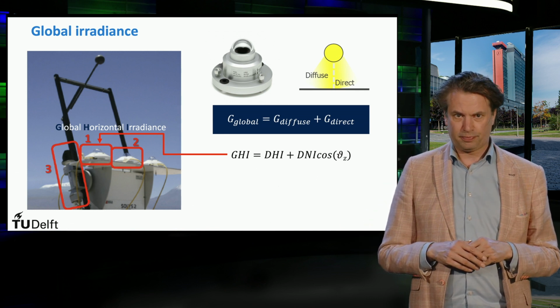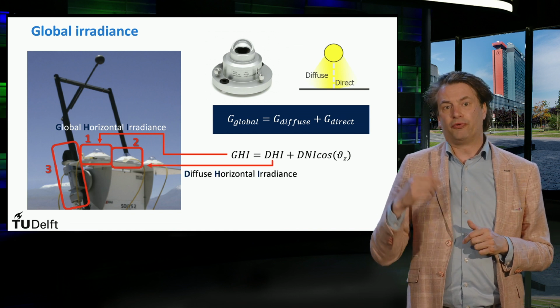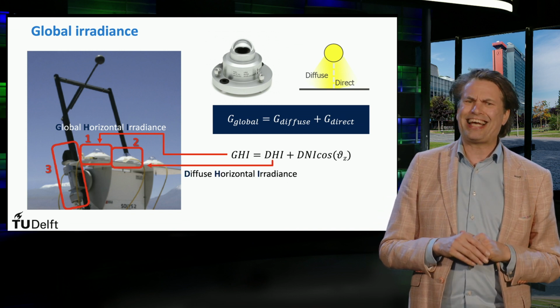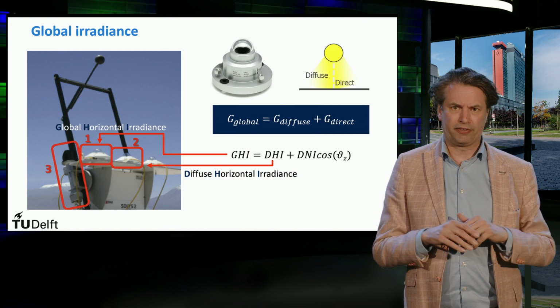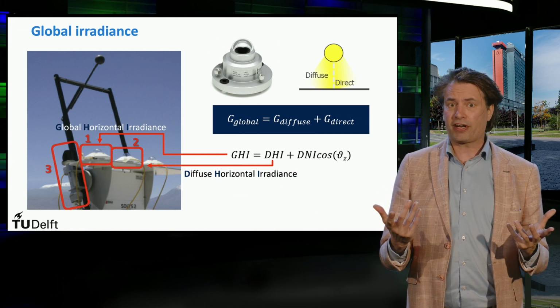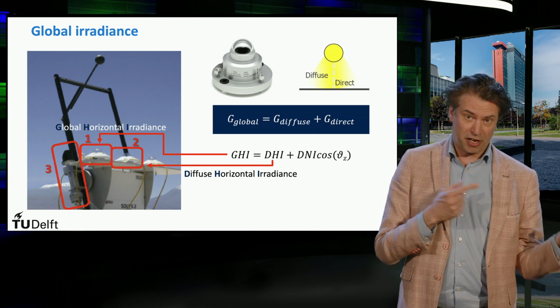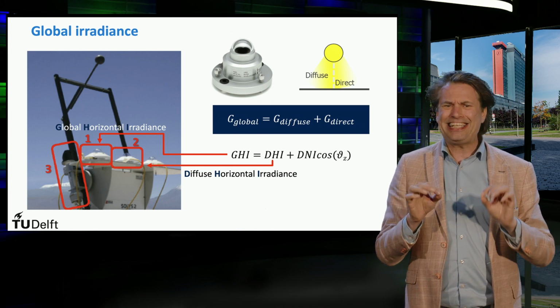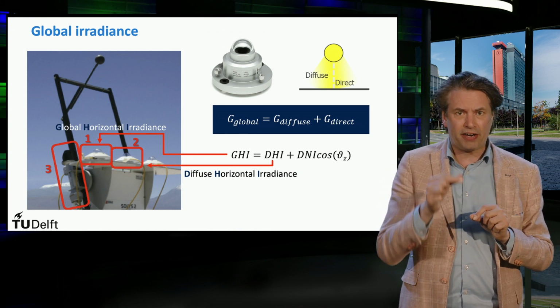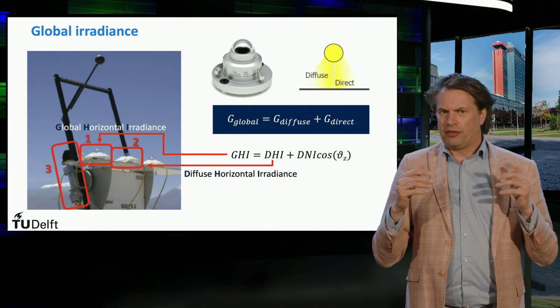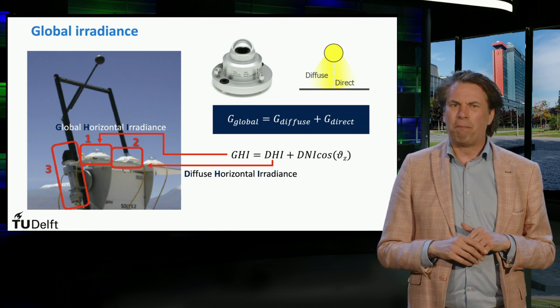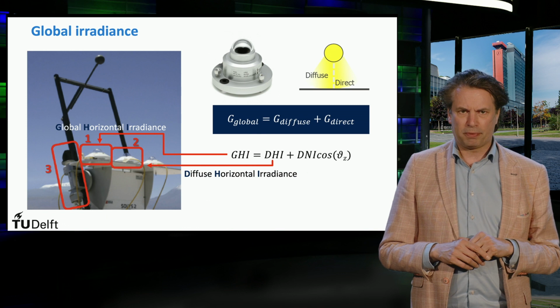Of course, this should be set as much as possible parallel to the ground where you will actually install the PV system. The pyranometer in the red box number 2 measures instead the diffuse horizontal irradiance. It has the same configuration as the previous one, but a shading disk obstructs the direct irradiance. An embodiment of the shading structure is the black ball here on top.